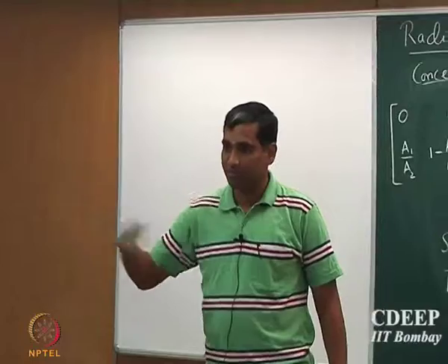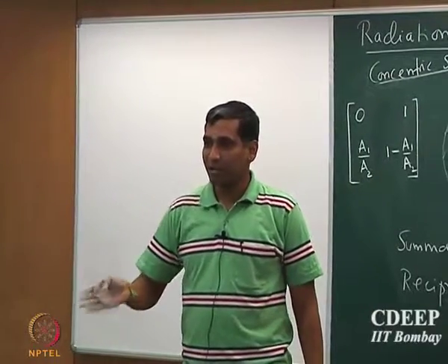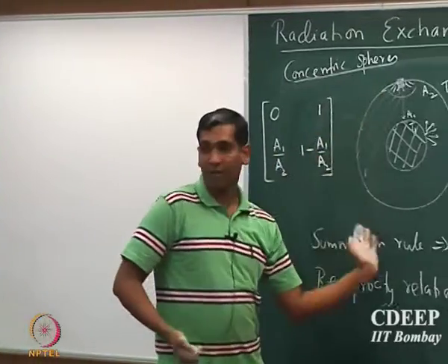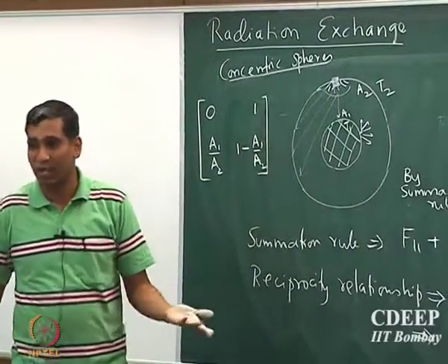It could be. So for example, you could paint with different colors and you could change the emissivity. So note that emissivity is a surface property. So you change the properties of some locations of the surface, you're going to change the radiation properties.